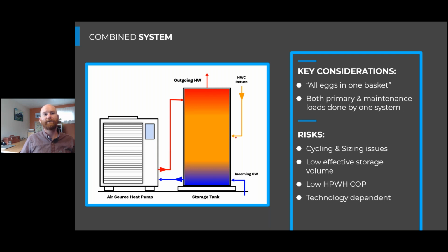But if we look at it over the course of an hour, it's a very small load compared to our primary load, so actually taking that hot water and making it hot for use. And so there's a sizing scale issue there. We might have this hot water load be 2 to 3 times more in scale than this return water load for our 100-unit building.